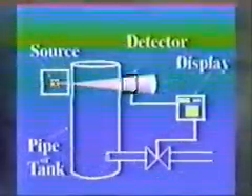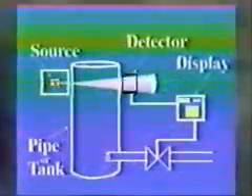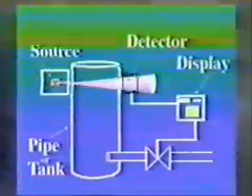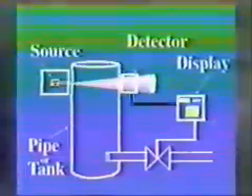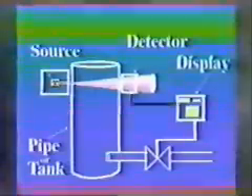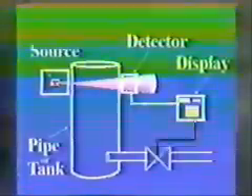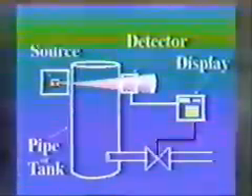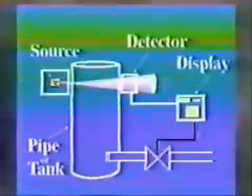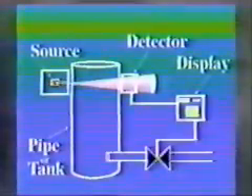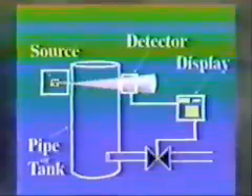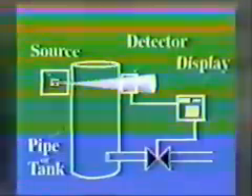The ionizing property allows the detection of the radiation at the opposite side of the tank or pipe. A signal is generated by the detector when ionization takes place inside it. This signal can be used to control processing equipment, such as valves or pumps, which keep the tank from overflowing or adjust the concentrations of input ingredients.